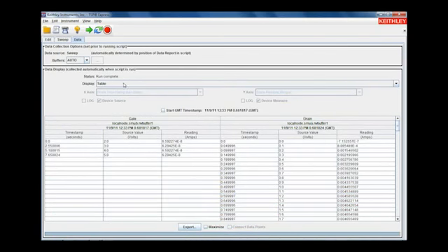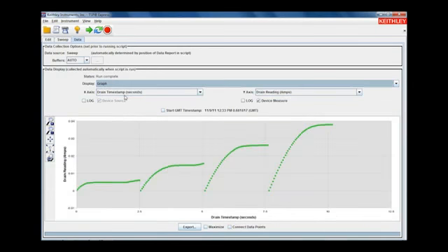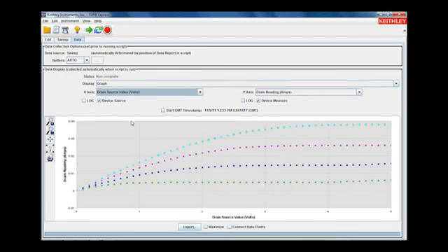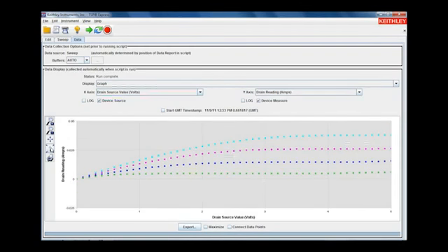This looks almost like what we want, except it's a little bit off as the curves aren't on top of each other here. So let's change the x-axis to volts. Here, now we see a typical graph of what we expect for a family of curves for a MOSFET. We can zoom in or zoom to fit, however you wish to do that here.